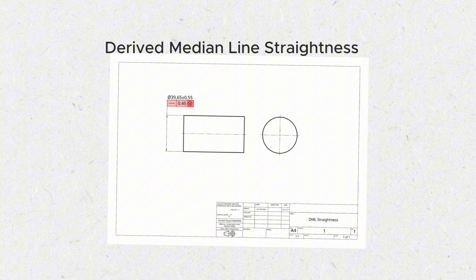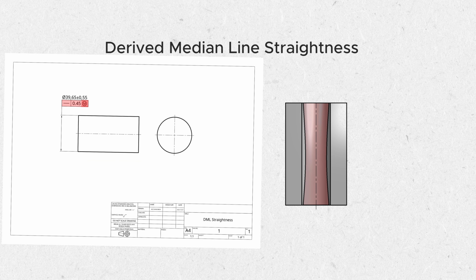To ensure that a part or feature is axially straight, a cylinder gauge is used to determine if the part fits in its total envelope at MMC. This controls the combined effect of the diameter and of the axial straightness. The ID of the cylinder gauge represents the maximum virtual condition of the part.